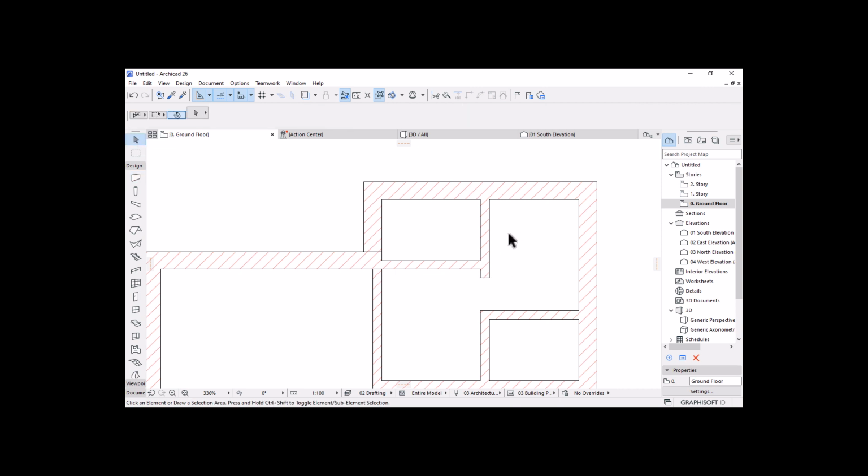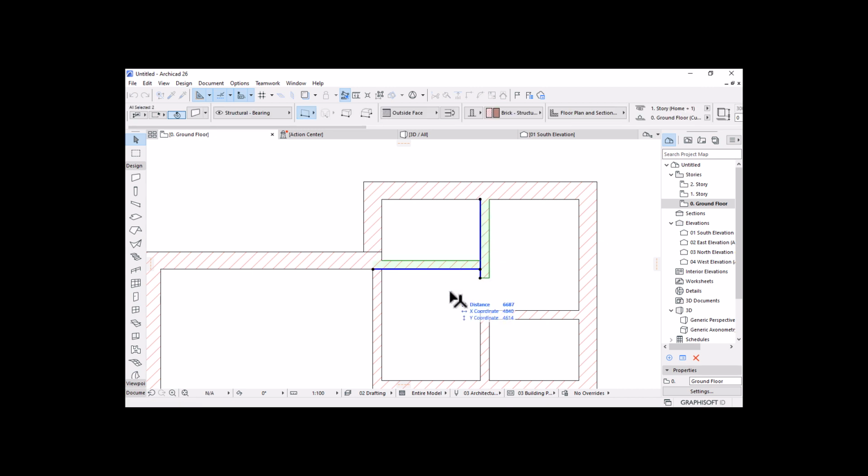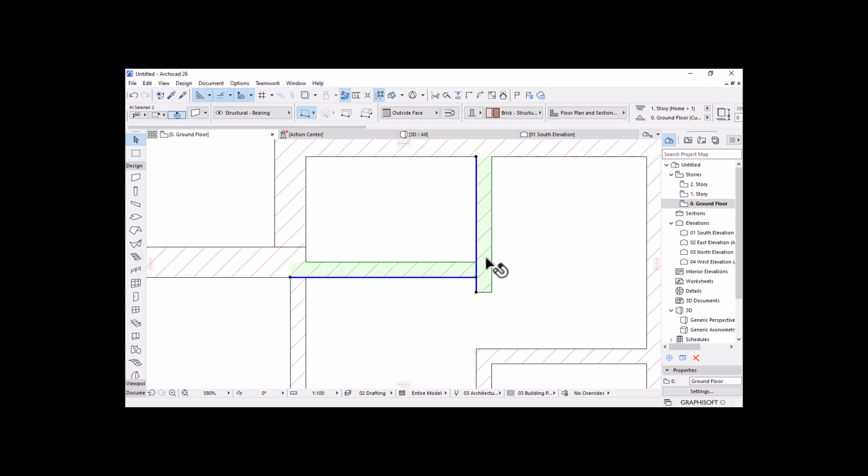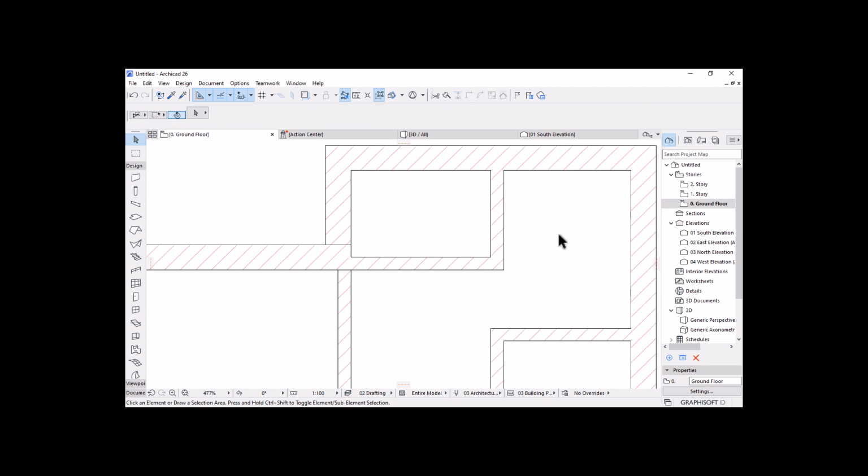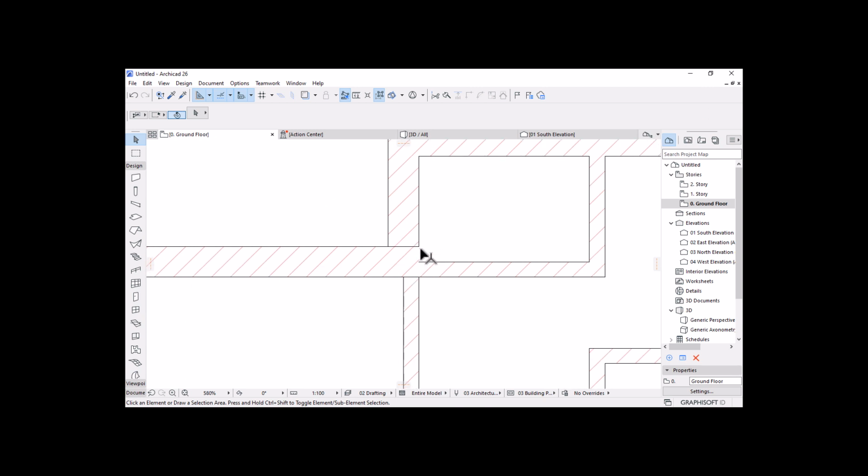I can now specify the first point here to select or diagonally affect these 2 walls, to select them, because I want to fix this corner to be a nice trim. So I'm going to use this intersect tool to trim that. Okay, as you could see, that's perfect. So I don't know what happened here. We have an issue of the connection. I think it's by introducing another wall to this junction here.